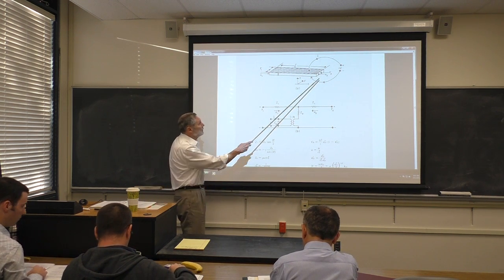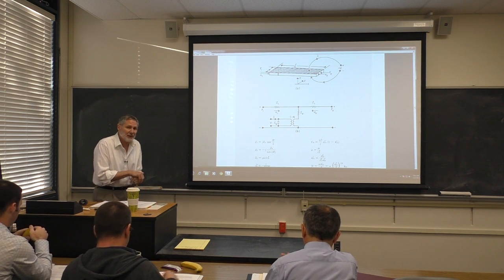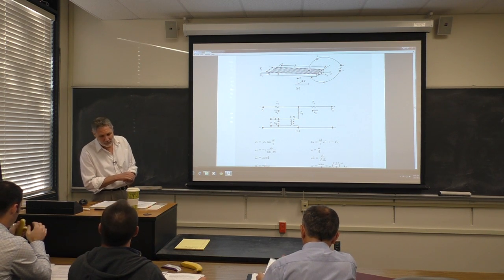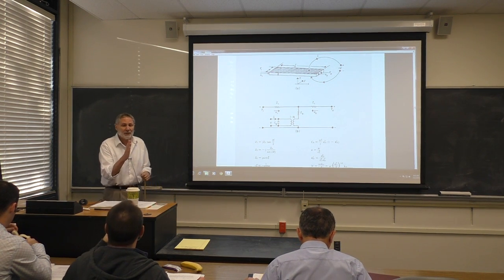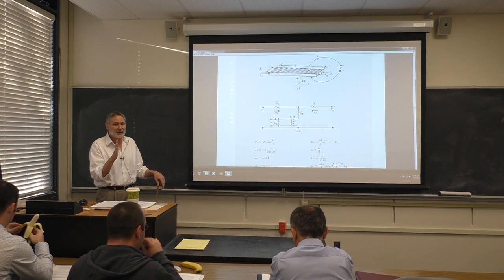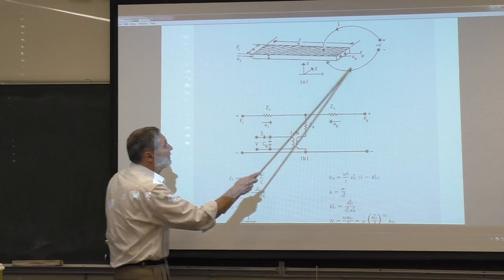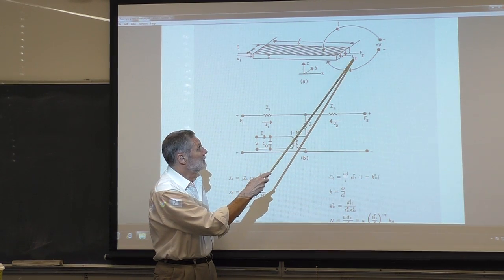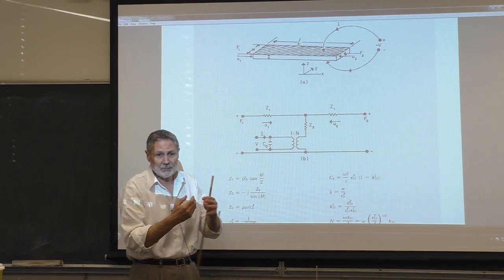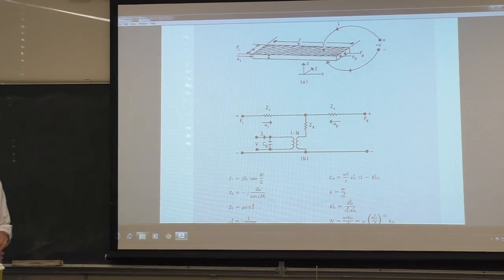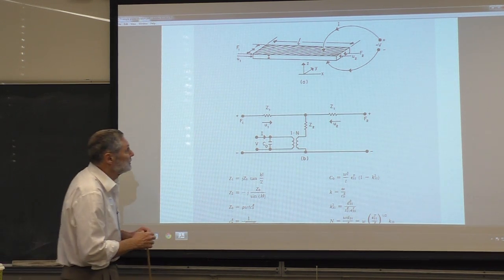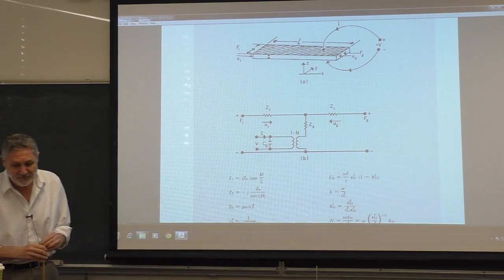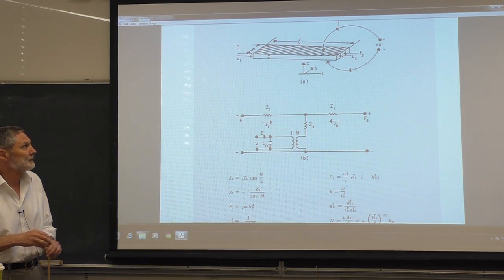But we did it for no load. Remember, we set the stress at the faces here equal to 0. There can be no net force on a face because the face has no mass. So if you've got nothing on the outside here and no load, on this side you would have in general a load. On the other side, you have the material. It can exert no stress. But there is a strain, which is different from standard classical theory of elasticity, and that's due to the piezoelectric nature here. So what we want to do now is generalize to a force.